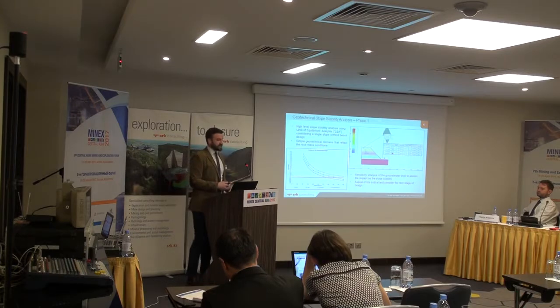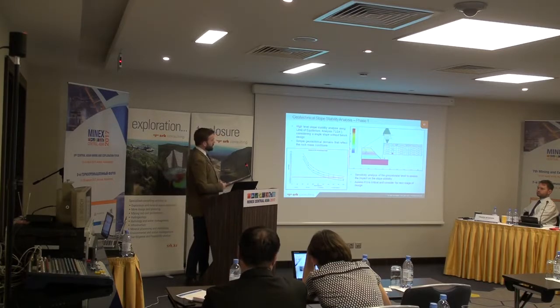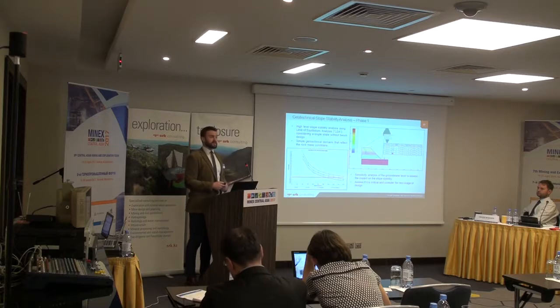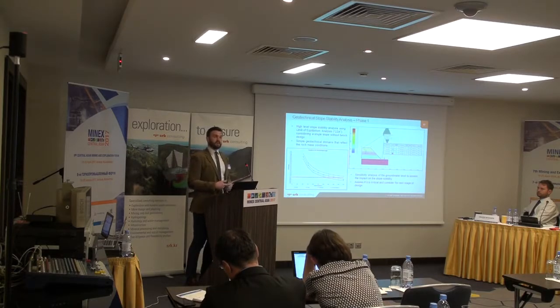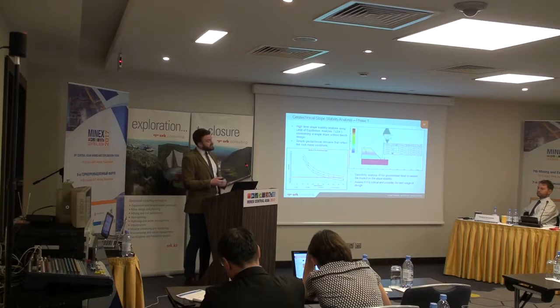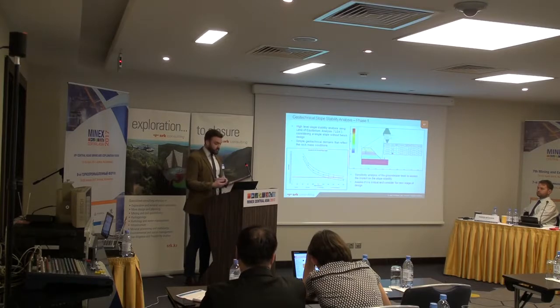That then is fed back into our mine planners, who then do a more optimised pit slope design and create a mine excavation sequence for the life of mine plan. And that's given back to a hydrogeologist then, and if groundwater is critical to the pit slope design, and certainly for dewatering of the pit slope, they will carry out more detailed numerical modelling of the groundwater conditions.